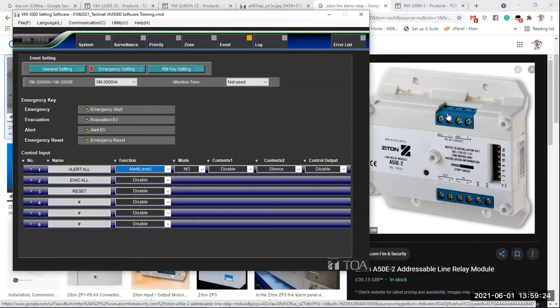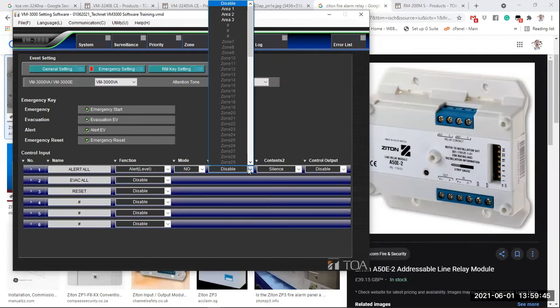If you are using the normally closed side of the relay to terminate your orange white or orange cable, you use normally closed. That's the difference. So the system is just asking whether my relay must be a normally open signal or a normally closed trigger signal. The default is normally open, which is very common with most installations. Once you've done this, you need to go to contents.